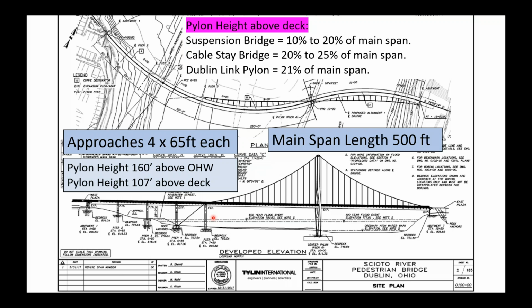And what's the load rating of the bridge? Load rating, I guess. Pedestrian bridge, it's a little bit different. You don't have a vehicle. We did design the bridge for an H10 truck, which is what ASCE requires for a PED bridge of this width. It varies between an H5 and an H10 depending on width. At this width, an H10 vehicle was the governing vehicle. So you can drive a 10-ton truck across this bridge without any problem.